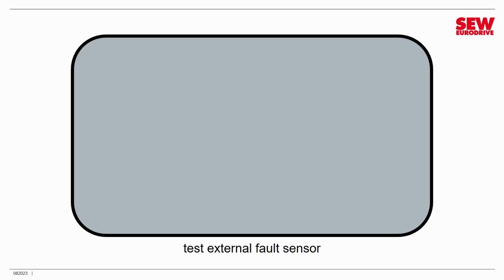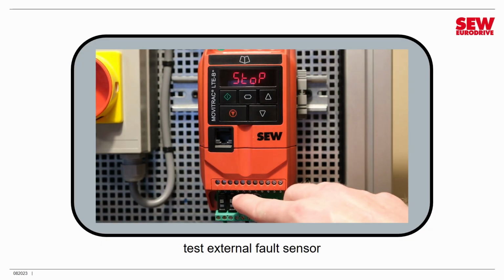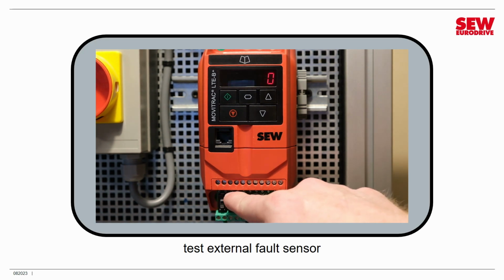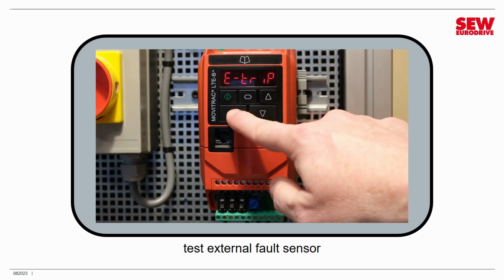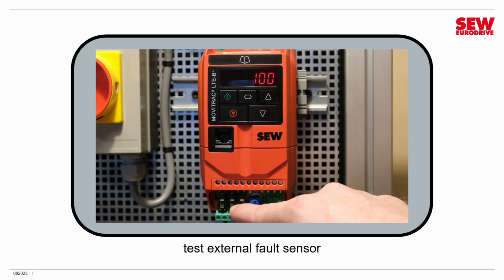All right, I'm going to turn the switch connected to digital input 3 on to simulate a normal sensor condition, and I'm going to start the drive, running at a preset speed. Now let's trip a fault. We're going to turn DI3 off. We get E-trip. Now I turn it back on again to clear the sensor condition, and I press stop to restart the drive. You notice it restarts immediately without warning.